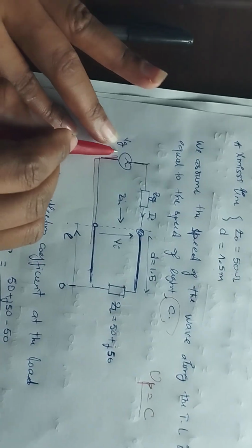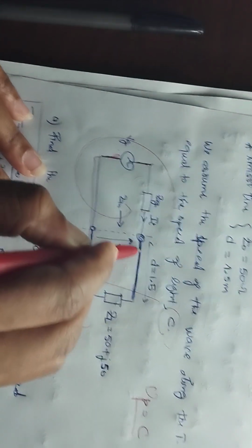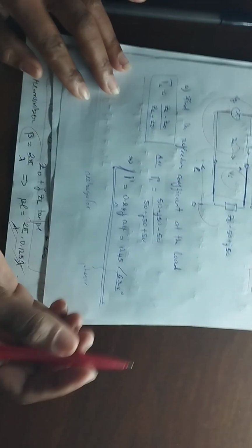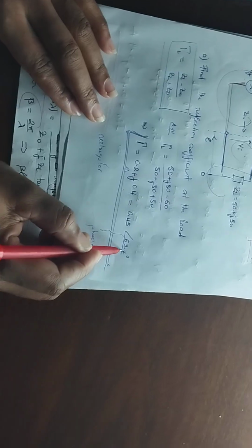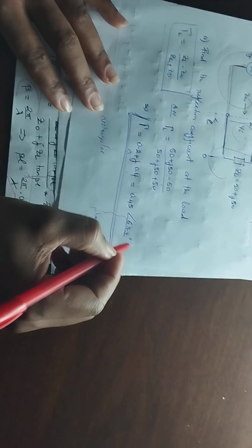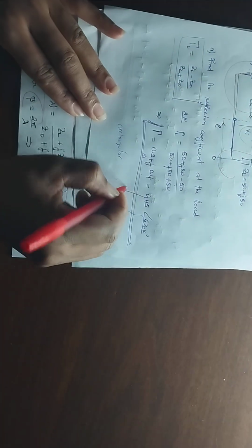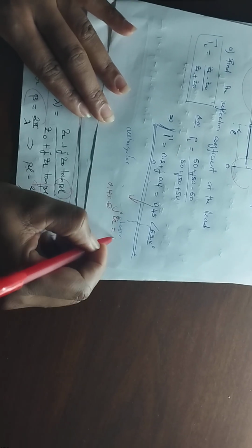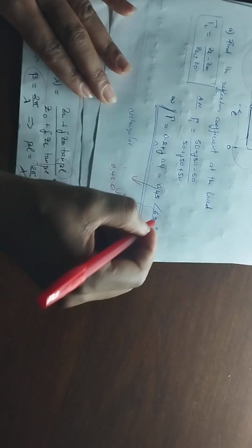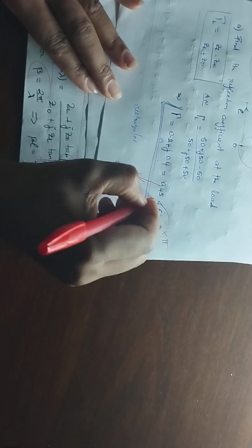So now this is my figure here, as you can see. I'll draw it for you. This is the source here, this is the load, and this is the information on the transmission line. To find the reflection coefficient now, we have to apply the same formula at the load. The numerical application is this one, as you can see. After having everything, we have this one in polar form and this one in phasor form. So again, I can write it as 0.45 e to the j theta L, and theta L here is 1.107. You just need to multiply this and divide by 180 degrees to find this one.